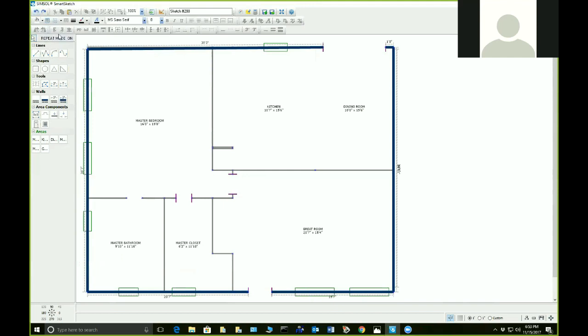And I'm going to keep the repeat mode off, and I'm going to left click on this line. I'm using the control key. What I wanted to do is send this to the back, which is real easy.